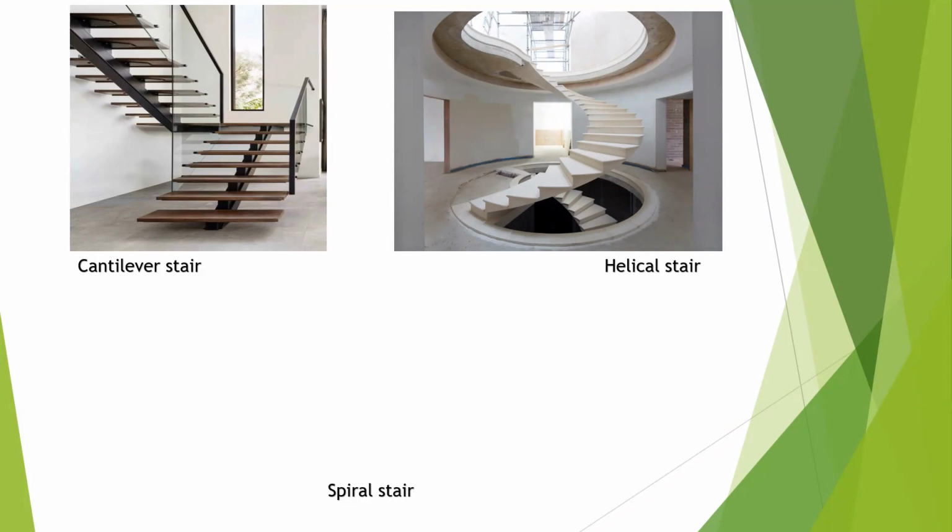And it is always a single straight flight turning as it rises, you see, okay? And one very important thing structurally for this kind of stair is that torsion at the end of the stairs must be taken care of. There will be torsion at the end of the stairs, and this torsion must be taken care of.